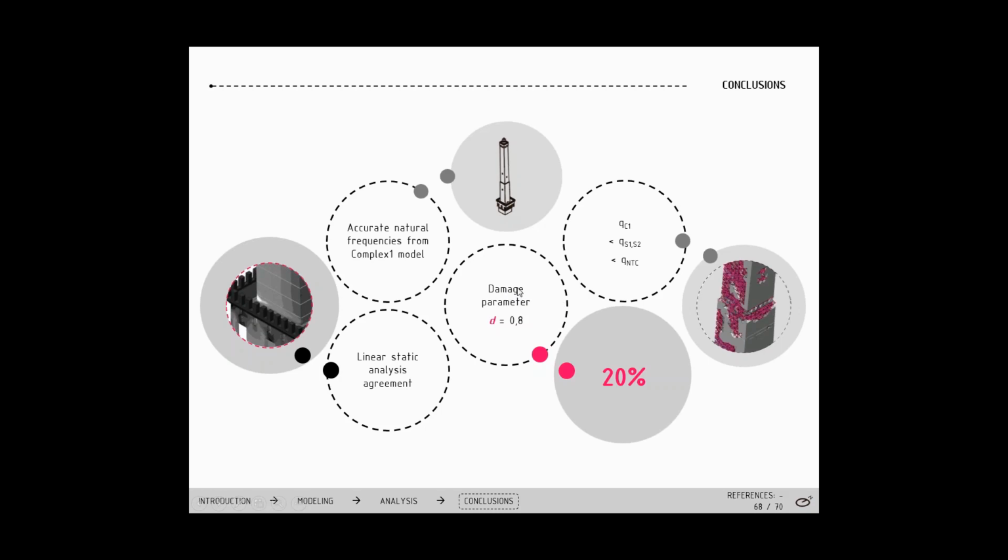Also, the introduction of a damage parameter that accounts for vertical cracking damage in the masonry becomes an efficient and easy to apply model, since the anisotropic model proposed showed the importance of considering the damage in structural analysis. Future and more detailed research is encouraged on this matter. According to this model, the Asinelli tower presents a 20% decrease in the mechanical properties in horizontal direction due to the presence of damage due to cracking.